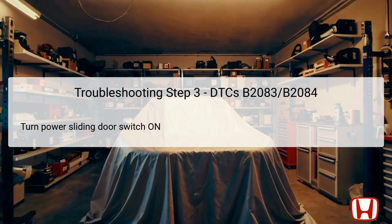Monitoring the switch's activity will also help determine if the control unit effectively receives signals necessary for the sliding door's operation. If the switch remains inoperative despite being turned on, it may indicate a fault in the switch itself or in the signaling circuit to the control unit. Observing the functionality at this step is crucial in narrowing down the cause of the originally reported DTCs.